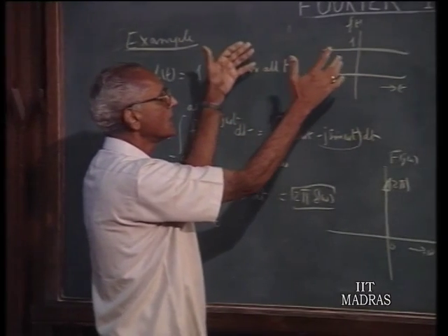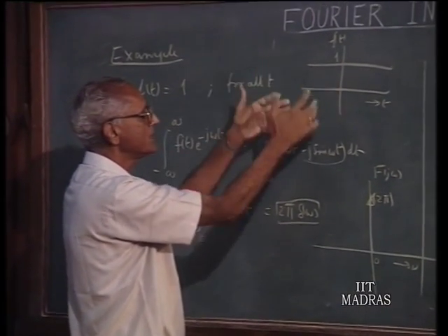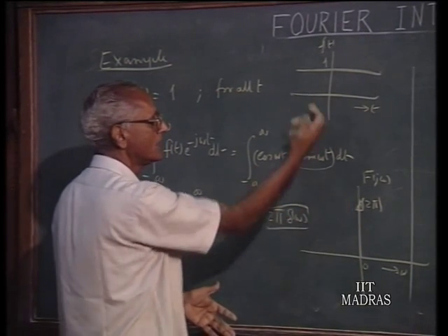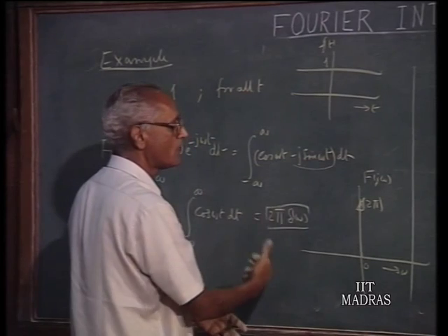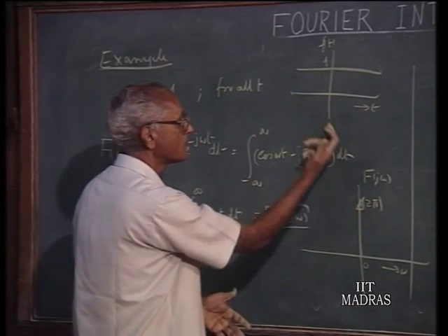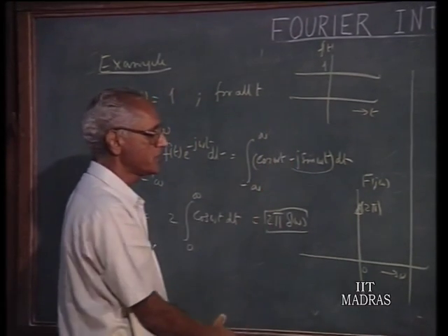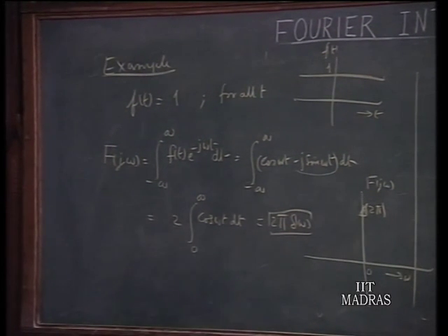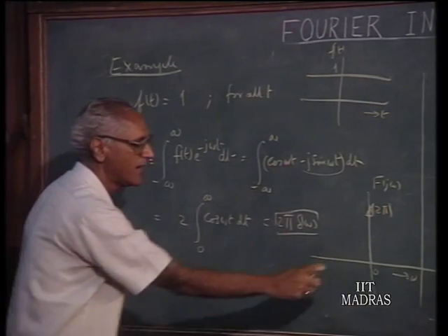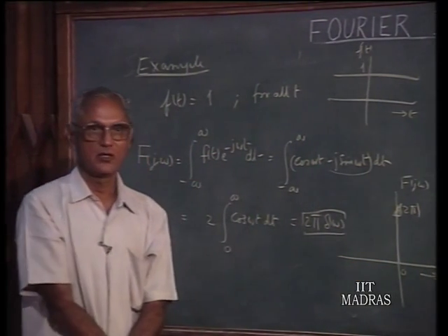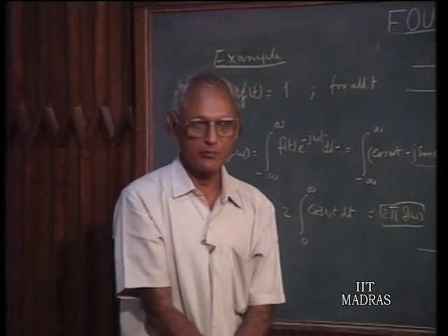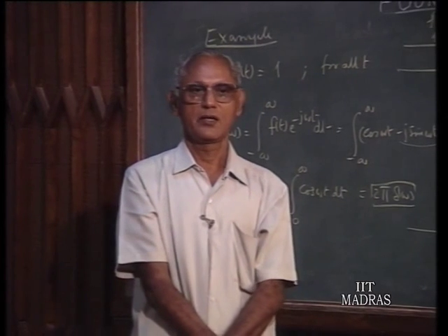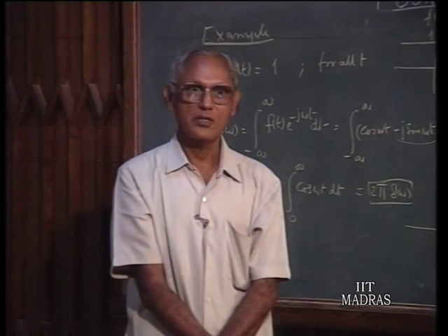and came up with the result, which perhaps could have been quite obvious, that this particular signal has only one frequency component, and that is DC. It becomes a line spectrum once again in the Fourier transform also, but there is a coefficient which is non-zero, therefore the coefficient density has to be infinite. Therefore we have a delta function: the coefficient density is 2 pi delta omega, and the density occurs at 0. And so we can expect that when we talk about periodic functions, in the line spectra, the magnitudes are going to be infinite, involving delta functions. More about this in the next lecture.